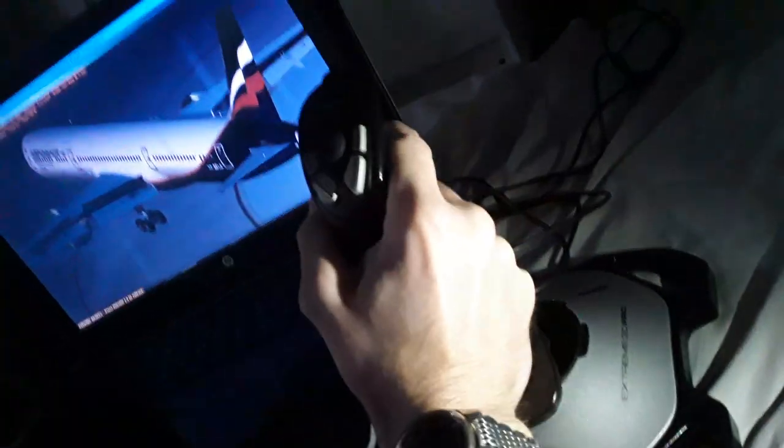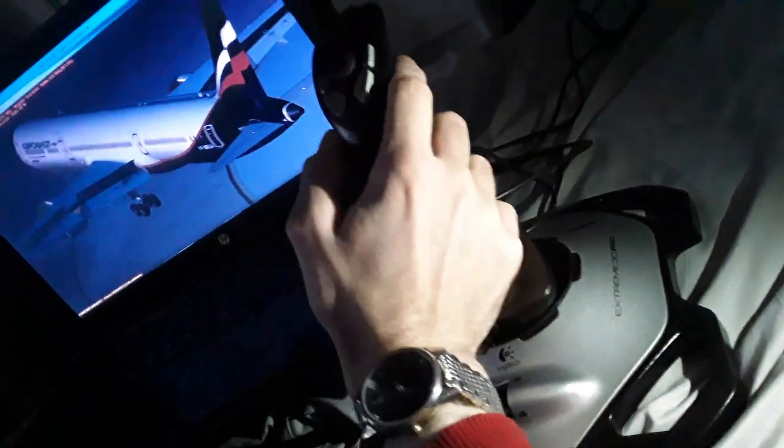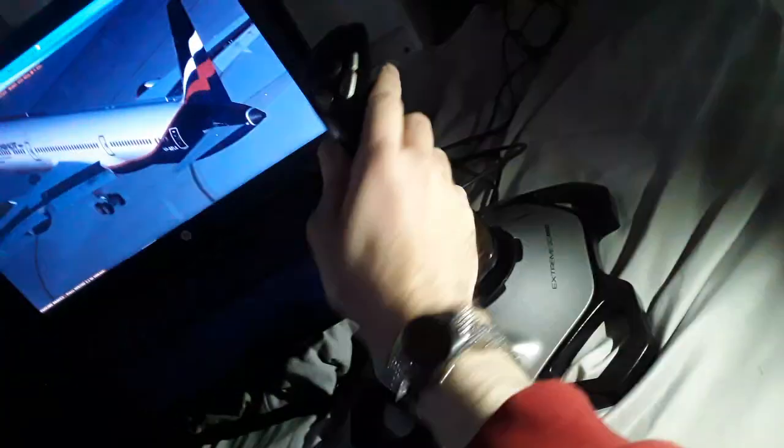Also in the Boeing you have, as I told you, the control wheel for left and right turns. So side stick left and right in the Airbus, and also control column up and down in the Boeing and back and forth in the Airbus. So this is all the flight control we need to know right now. As you can see, I hope you like it.